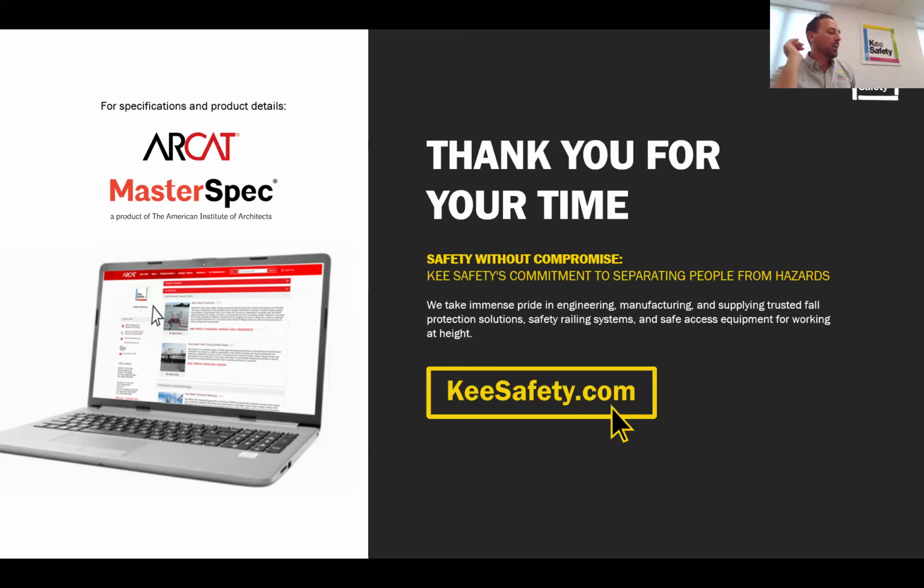So yes, a parapet does meet the fall protection requirements for a barrier along the leading edge if it's 42 inches plus or minus 3 inches. So the lowest your parapet can be is 39 inches to be in compliance. A lot of clients that I have, they'll have like a 30-inch parapet, and they'll be like, well, I'm close enough. It's fine. Don't worry about it. That's not a good answer, and it's all about physics, right?